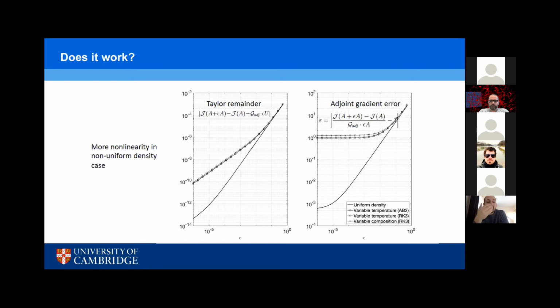And it has been seen in other studies with continuous adjoints that finite difference calculations for the gradient tend to suffer from irregular behavior after a certain point due to round-off errors in finite difference schemes. So I am not concerned that this is just within the realm of what we expect.